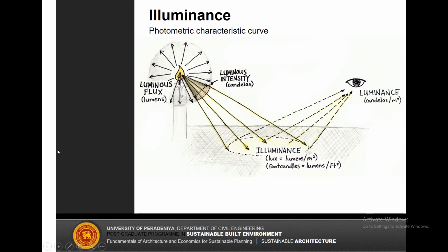So clearly understand this difference between lumens and candelas, the luminous flux and the luminous intensity. This is related to angle. Light energy per solid angle is called the luminous intensity. The total light energy of a light source is called the lumens, the light energy output or the wattage kind of thing. Okay, luminous flux, luminous intensity. I think it's clear for you.